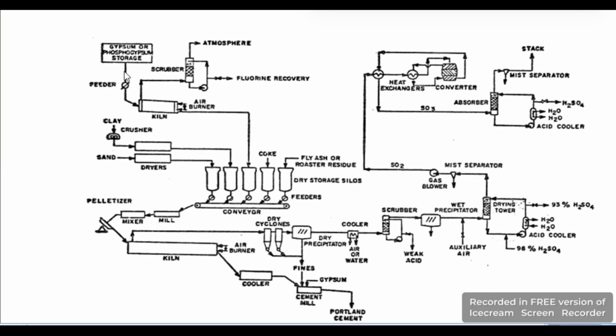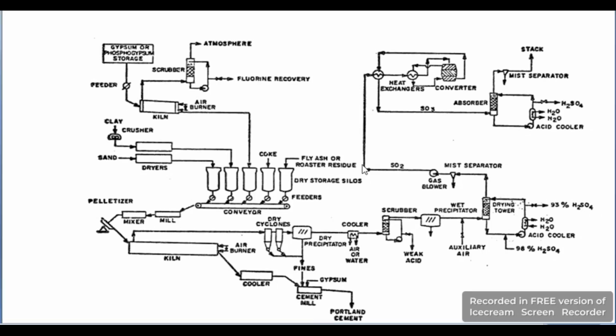After clay and sand, some other raw materials or recycled raw materials are also entered into feeders, through which a calculated quantity is sent into the next section, which is the milling section, and through these mills the size of that mixture is reduced.